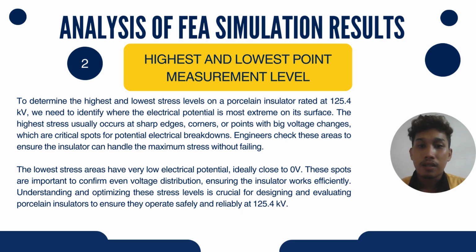The lowest stress areas have very low electrical potential, ideally close to 0 volts. These spots are important to confirm even voltage distribution, ensuring the insulator works efficiently. Understanding and optimizing these stress levels is crucial for designing and evaluating porcelain insulators to ensure they operate safely and reliably at 154 kilovolt.